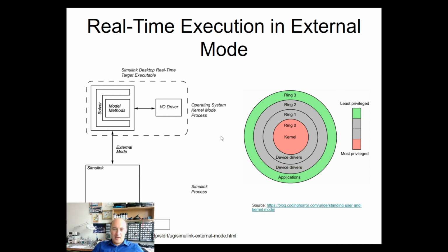If we want to have real-time control, we need to execute the code at the same priority as the kernel. So it will basically run with the same priority as the operating system. Hence, it will not be interrupted by other applications. And if the hardware is fast enough, we can run it in real time because we have a defined behavior with regards to sampling frequency.